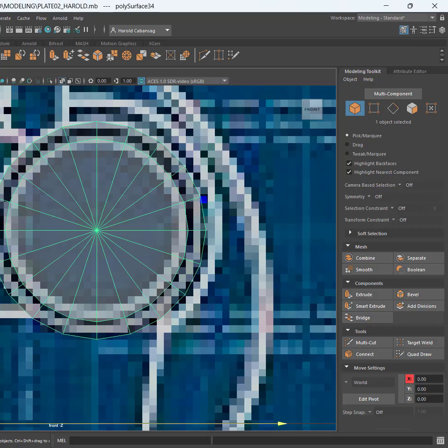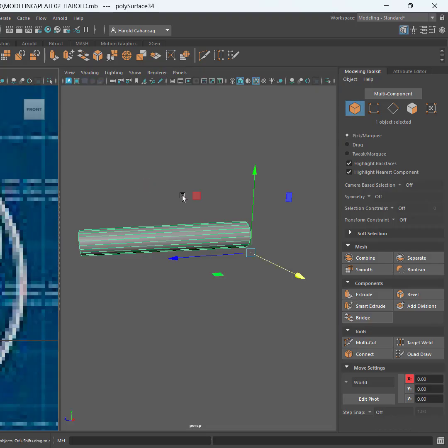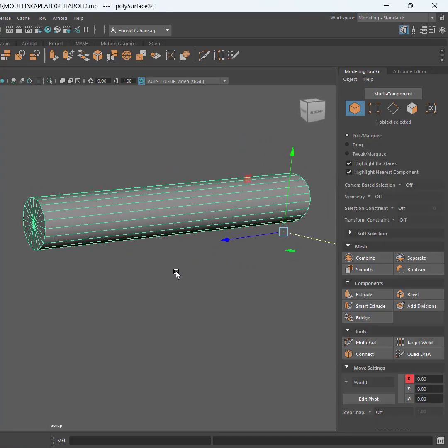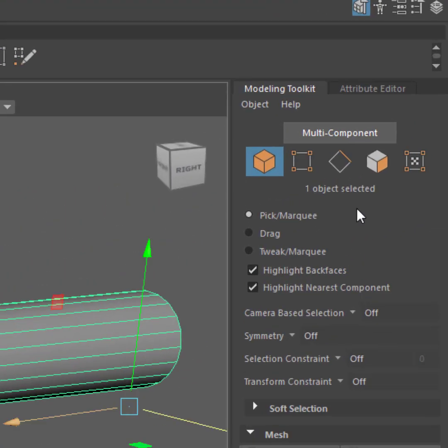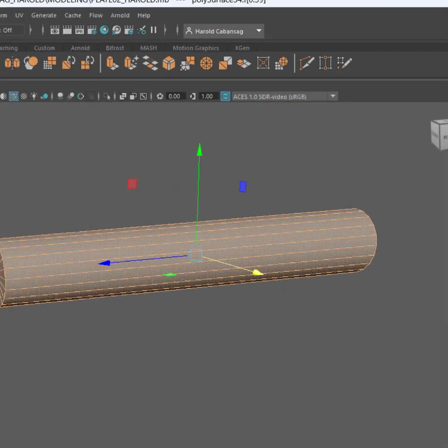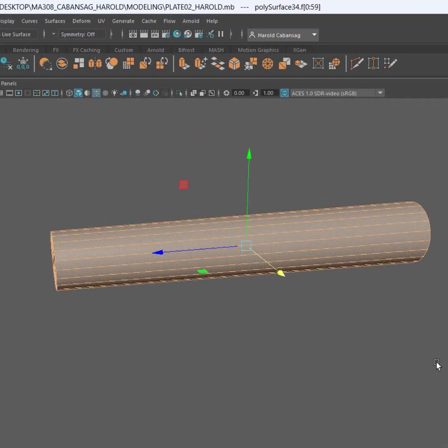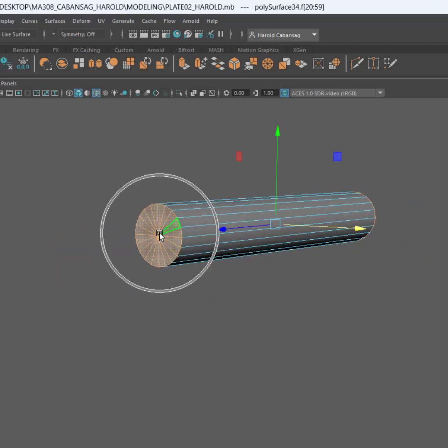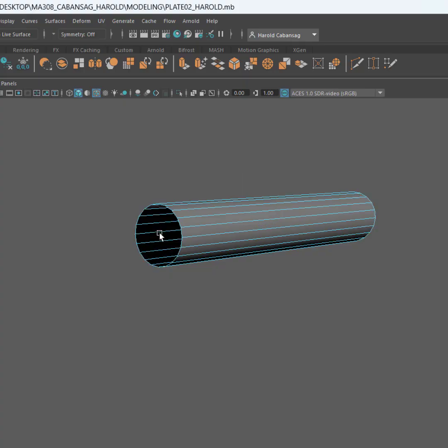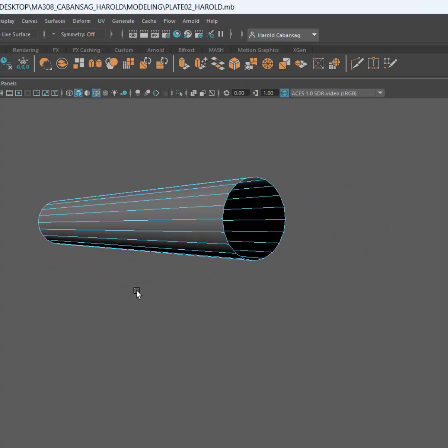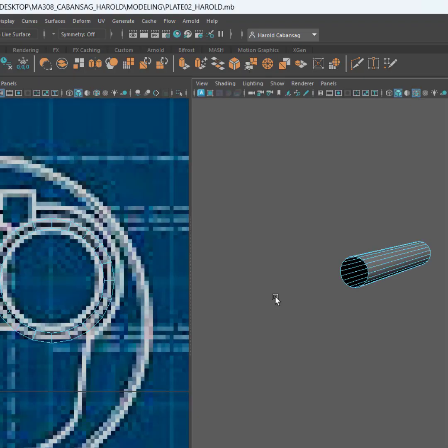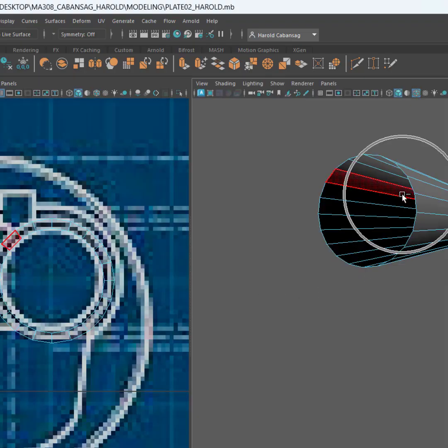I'm checking by using this. This is the gizmo. Then, let me reduce that. After that, I will start deleting polygons that I don't need. For example, I'll switch to the polygon selection. I'll select all of these, and then I will hold control and deselect these polygons because I need to hollow out the center of this, deleting that way. Okay, and then the next thing I'll do is to add thickness to this.